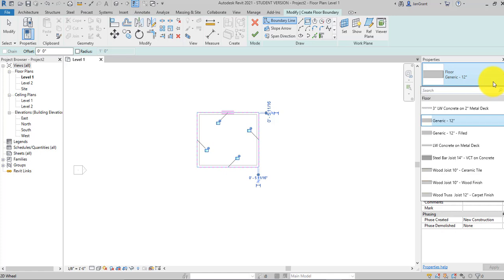And also, in order for us to use the tools that I'm going to work with you here with, we're going to make the floor a 10-inch instead of a 12-inch, so that we can have the 9.25 inch 2x10 joist and the 3/4 of an inch subfloor plywood.